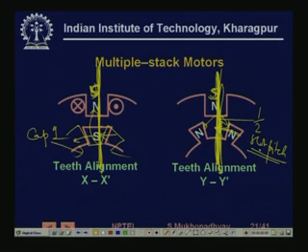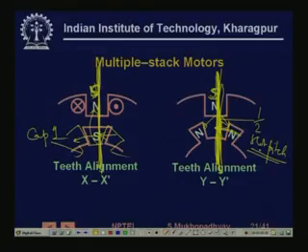You have the same kind of excitation, but a hybrid motor utilizes both the principles of rotor slots and one strong electromagnet, so you do not need so many magnets. So, you can have half the step angle.